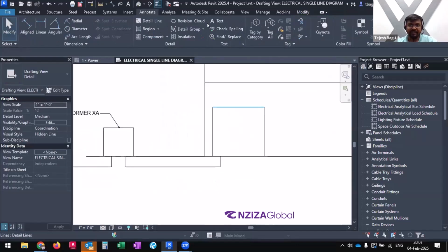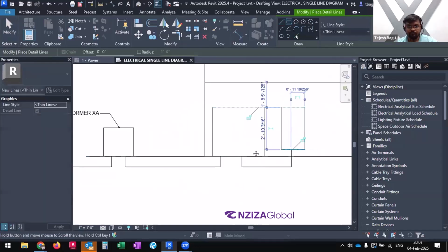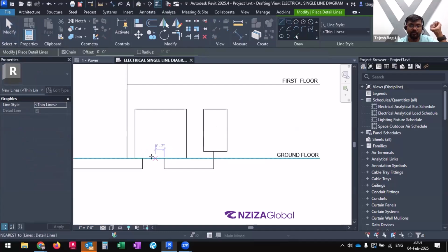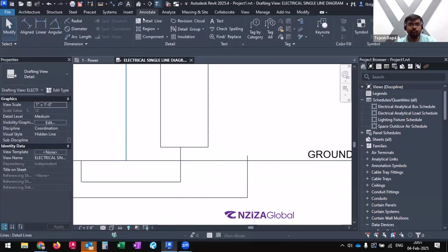Right. And then we will have the switchboard that would be feeding the individual panel boards in the given rooms. Right, so this is, let's say, the utility panel board that we had for the surgical room, for the operating room, and then we will have another line, let's say, going for the UPS. So it will go to the UPS first, it will feed the UPS.